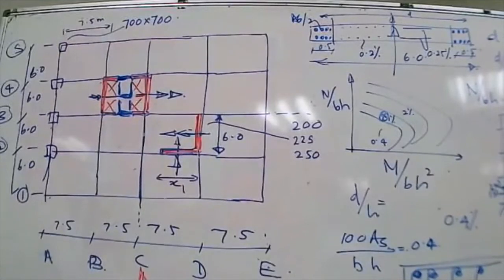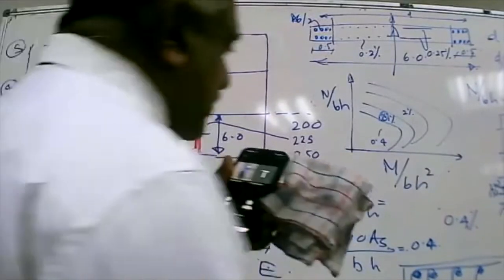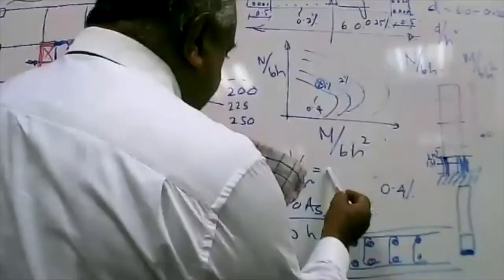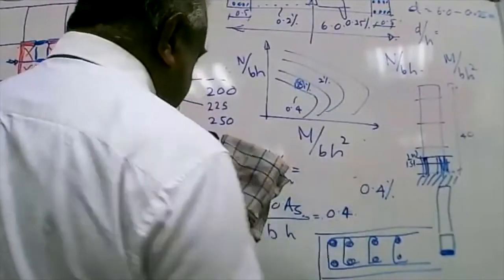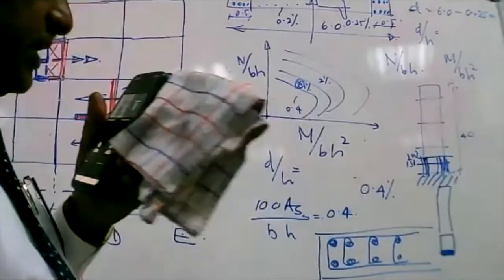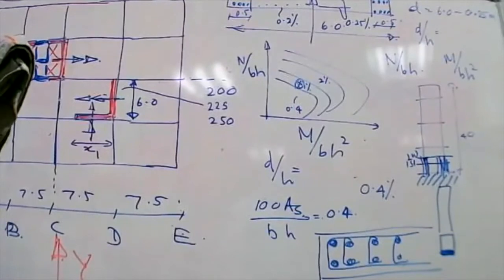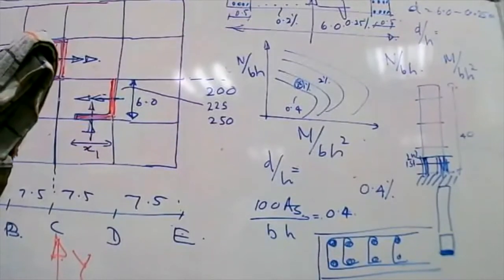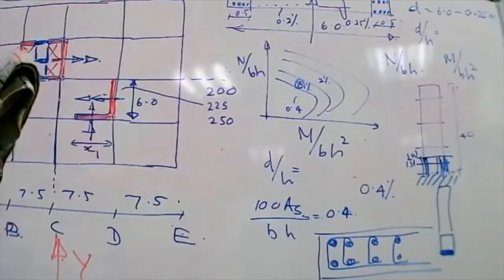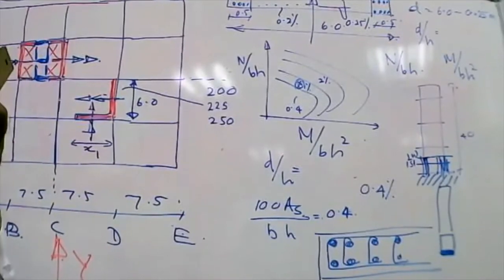Those interaction charts will have fcu, fck terms also, right? But it doesn't matter. They are all the same, because rather than developing different charts for different concrete strengths, they have developed one chart up to 50 megapascal concrete. Any other question?